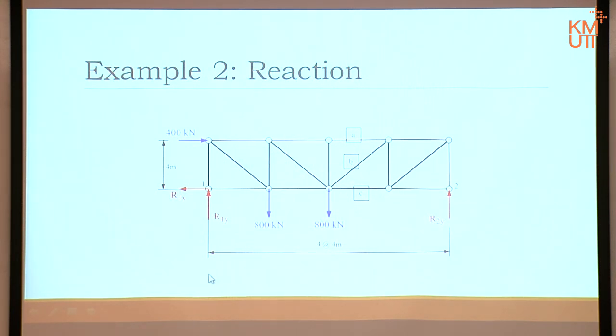If I look at the left hand side, I need to know R1x, R1y, otherwise I can't calculate it. Correct? But if I look at the right hand side, I only want to know R2y. What I'm suggesting here is that to analyze this question, I only need one reaction, which means R2y, if I choose the right hand side picture after the cut. Then I only need one side. Sigma moment about point 1 will give me R2y straight away, and then I will start cutting it.